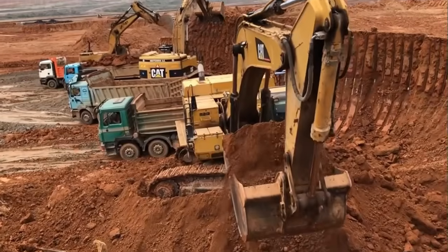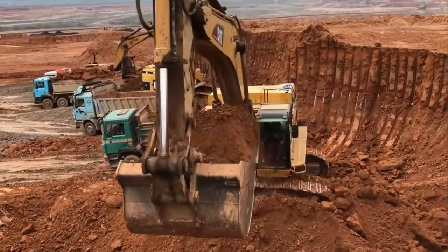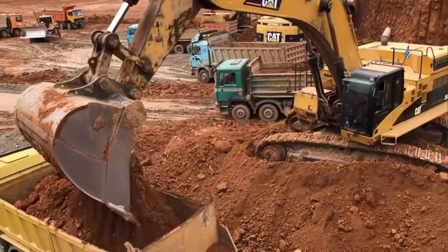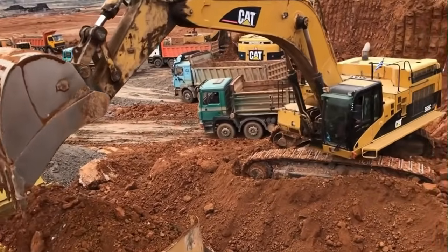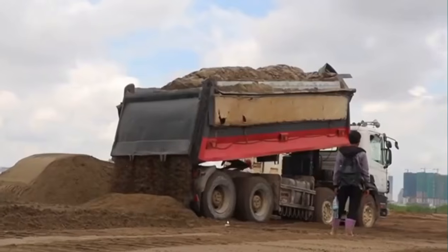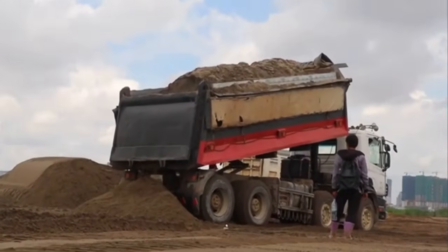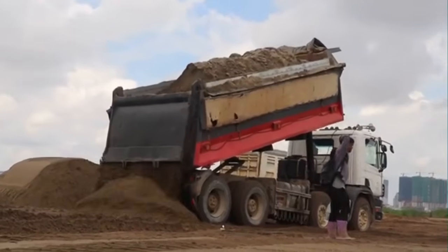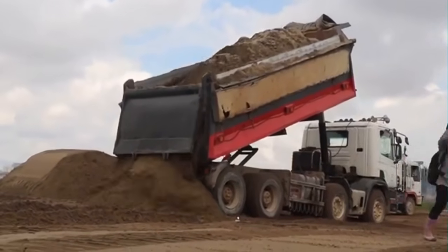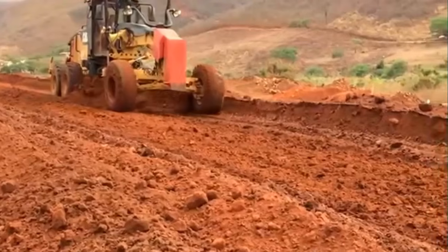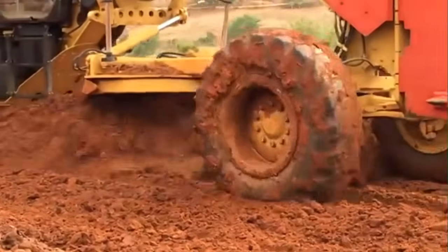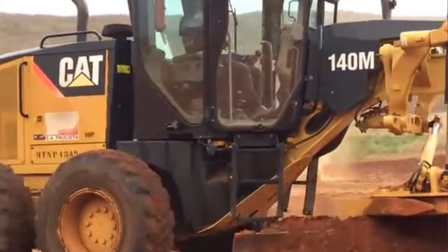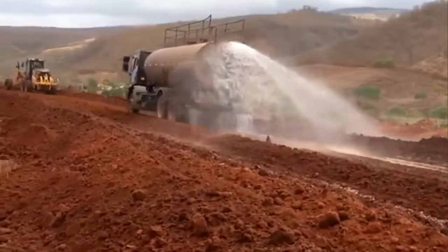It will be overlain by the other pavement layers. If the ground is structurally weak, likely to be subjected to exceptional loads, or is significantly below an ideal formation level specified, subgrades are layers of earthfill from a selected borrow pit. The scope of work includes excavation, loading, transport, laying and leveling, watering with potable water to optimum moisture content, and thoroughly mixing it before compaction. The compaction shall be done to 95% of relative density. For highways, the modified Proctor density is considered to find the relative density.